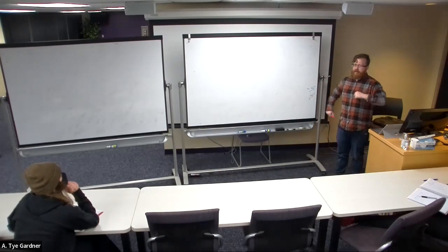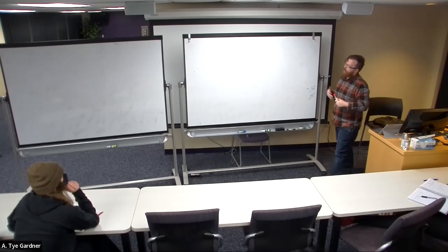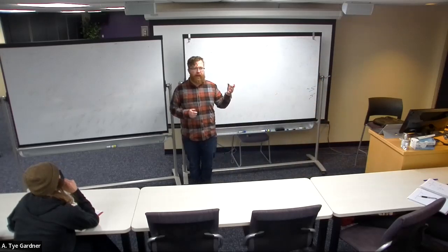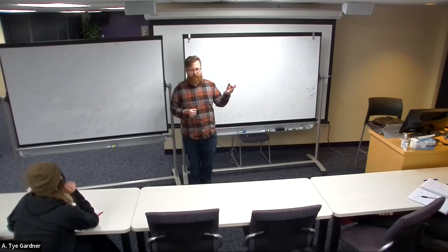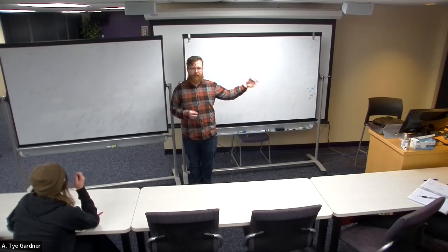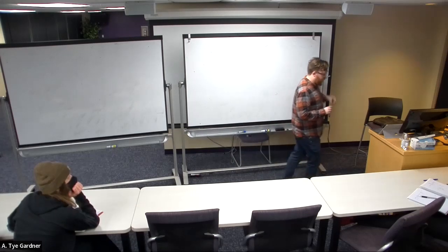Now, the reason I'm talking about Boolean algebra is because it is something of a nightmare. You don't quite fully appreciate that nightmare if you haven't done the homework yet, but you've seen me do it and you haven't gone through the motions. But there is a better way of simplifying circuits, and it's called a K-map. And the nice thing with K-maps is you can then use them to verify that you did it right. You can check your Boolean algebra with a K-map. However, in the homework, you need to answer it using Boolean algebra because I say simplify using Boolean algebra. I need to see that you know how to do the Boolean algebra, so that I know that you understand that process before you use the ECE tool, which is a K-map.